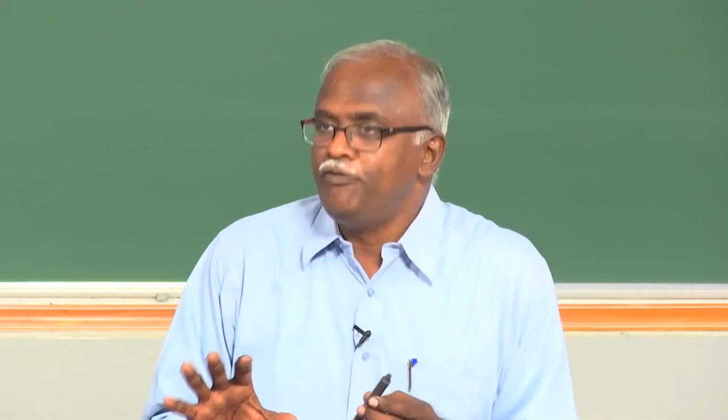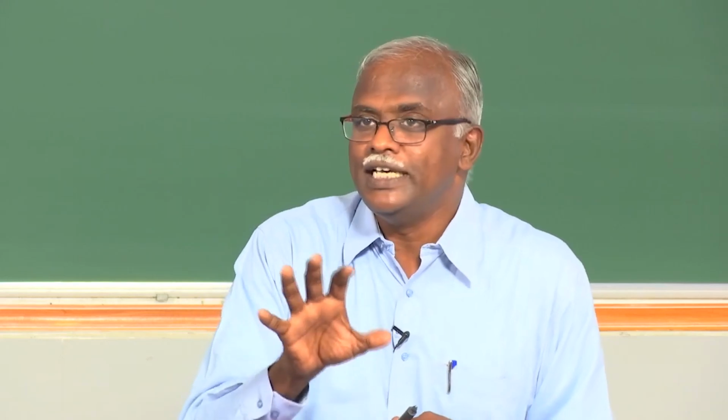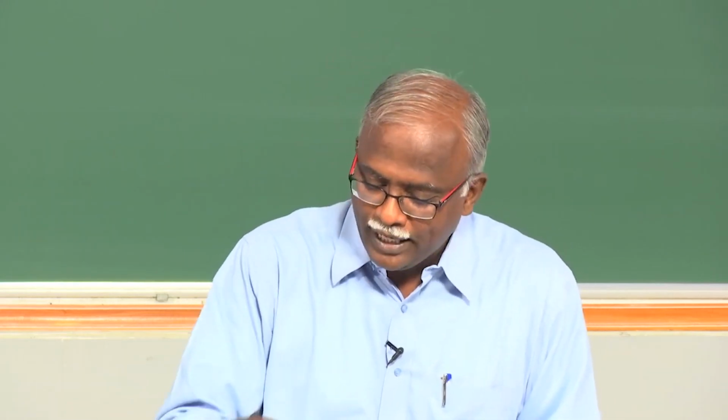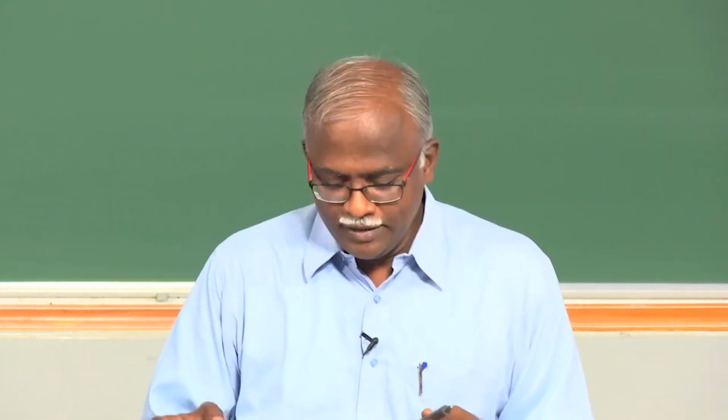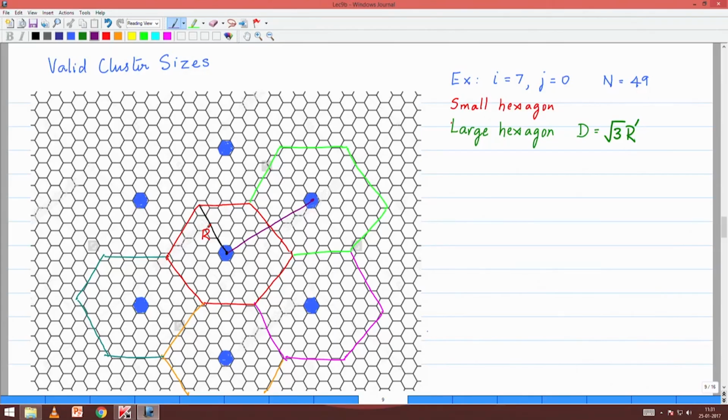Now think of it that these clusters, whatever the shape of the cluster, has to fit around each of these co-channel cells. And if you think of a large cluster size, then what you will find is that the shape that actually fits should approximate a hexagon, because only then 6 of them will fit around with these 6 points as the centers of those hexagons. For some people it's very easy to visualize that only then it will fit. But you may say, well, some of them are jagged, but approximately a hexagonal shape is what it will need to actually tessellate on this framework.